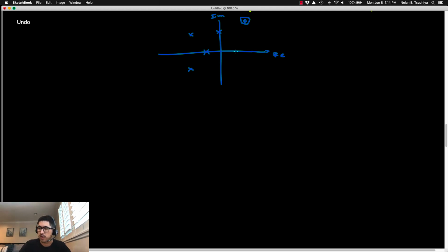If I were to do the following, right? So maybe I have three poles here and one pole over here. Well, this is an unstable system, right? I've got four poles total. Three are in the left half plane, but I've got that one unstable pole. The system is unstable.